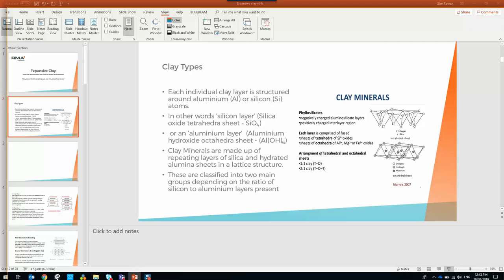Now the other one, I think I started using this 25 years ago, when you do a lot of sheds and commercial buildings in black soil, and it gets really expensive if you want to suspend the whole building. You're talking an extra over a 150 slab on ground to a 170 suspended on piers, probably $180 to $200 a square metre. And if they've got big sheds, people balk at that.